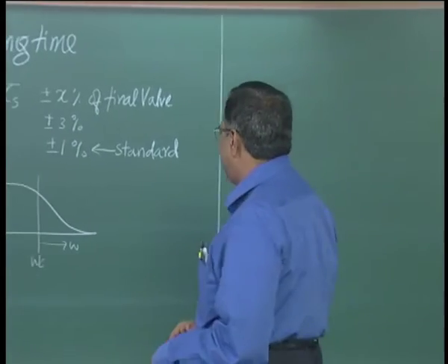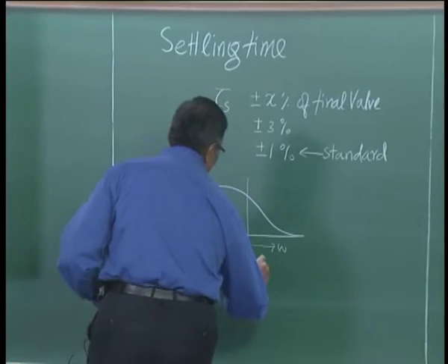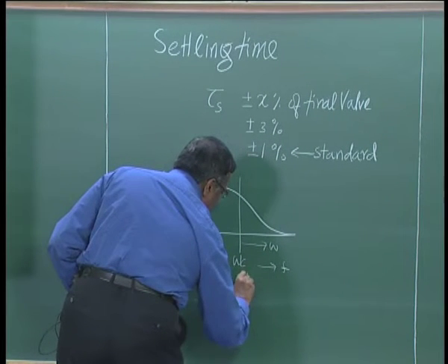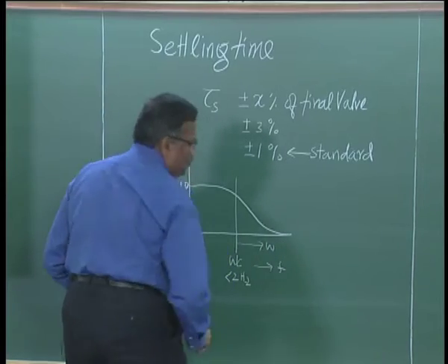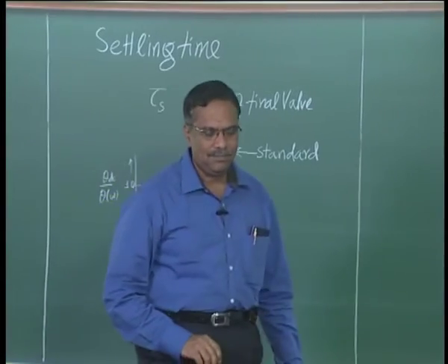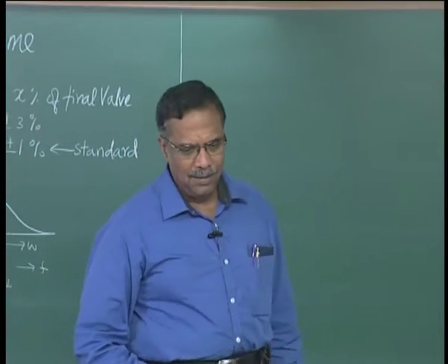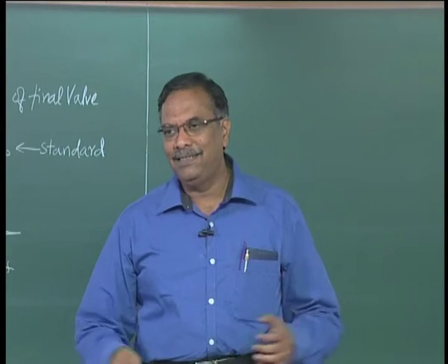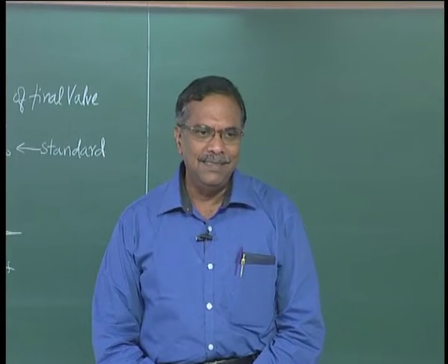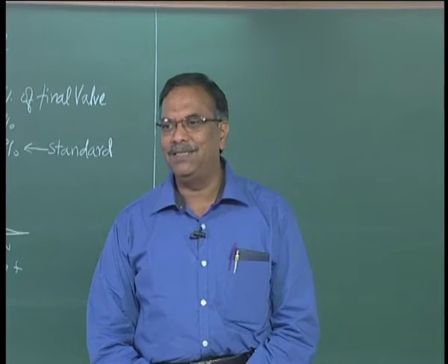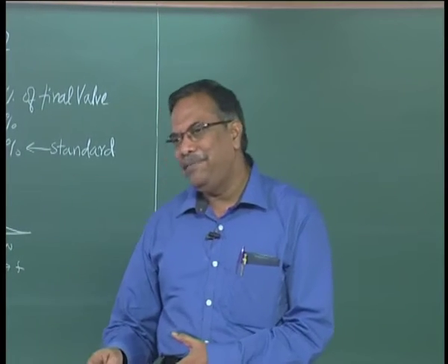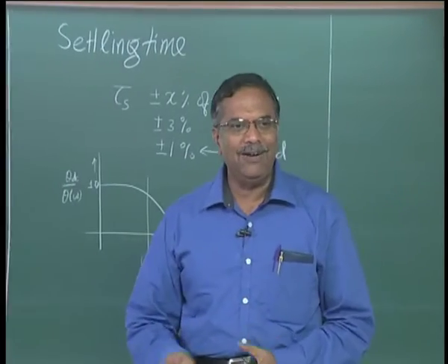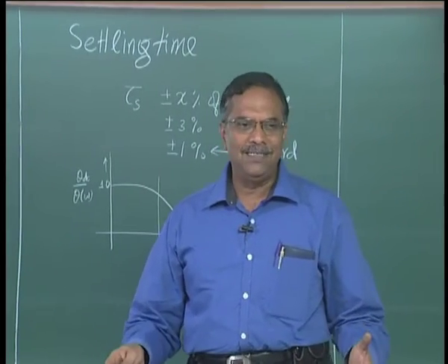So if I look at this in the frequency domain, if I put this as f, then this will be about 2 hertz, less than 2 hertz. So this is another reason we keep saying that the PMMC meter is a DC meter, because even if I want to make it an AC meter, the mechanical system natural frequency is small and I cannot measure even 50 hertz, right.